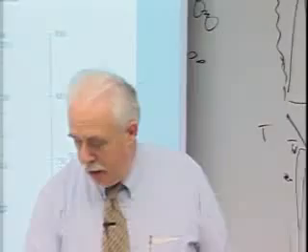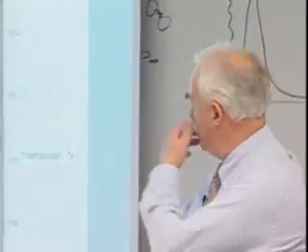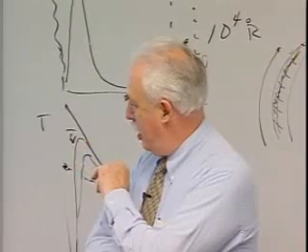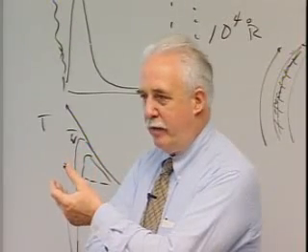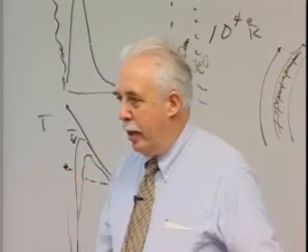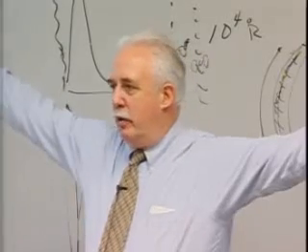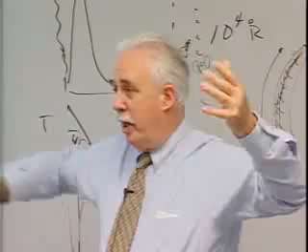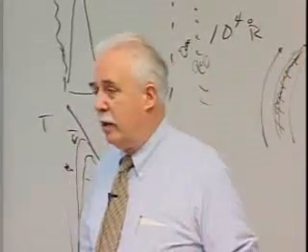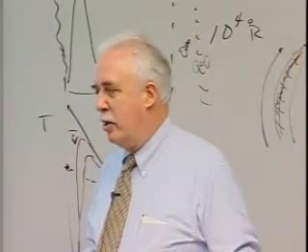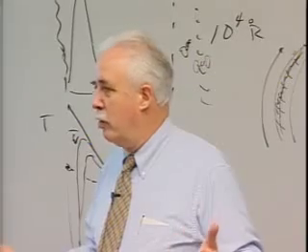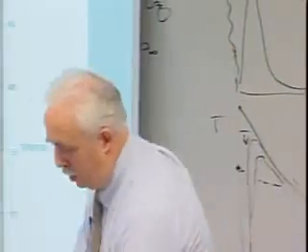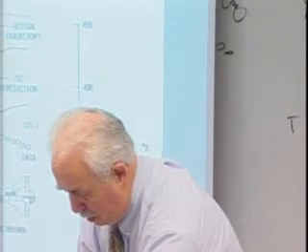The other thing in the shuttle, which I'm sure Tom discussed, was the thermal stress. I mean, if the belly gets heated and the wings don't, the whole wings pop up, okay? That is one big integrated problem, which gave us a lot of difficulty. Again, with the simulation and computational capability we have today, I think we can do a much better job of that. And also just understanding the importance of it.